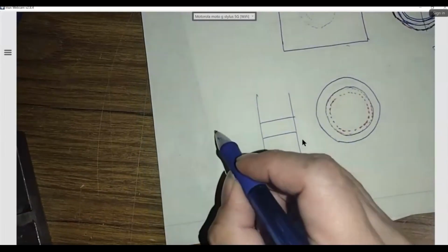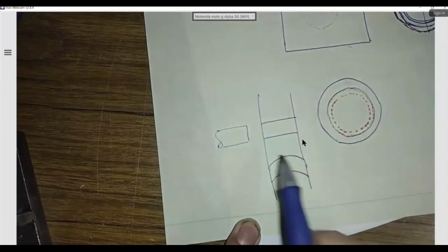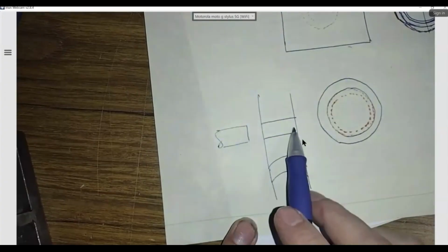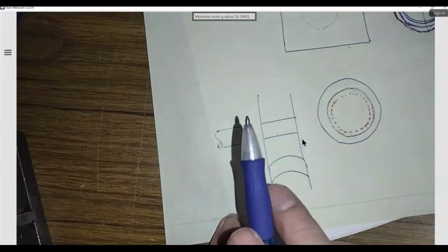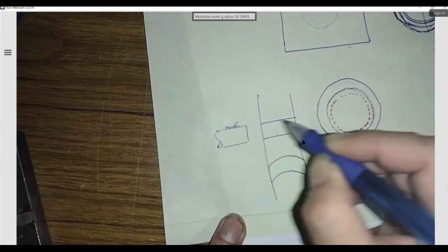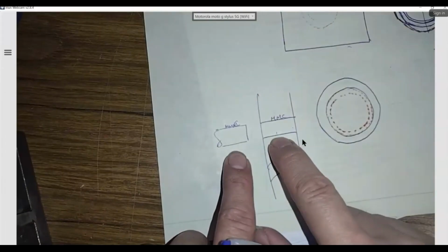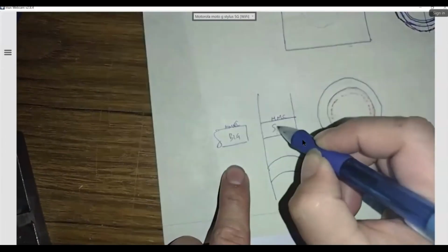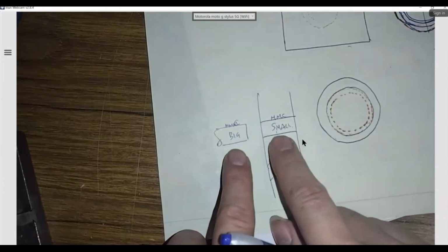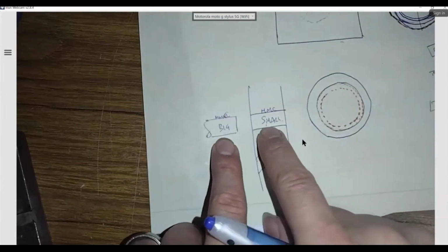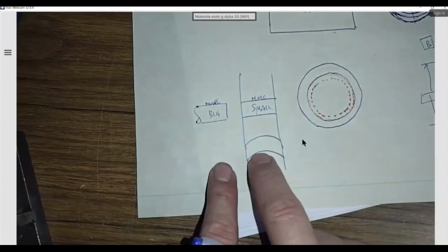What happened to a pin? So if I were to have the pin, and my hole were to be perfectly straight, even at the worst case condition of the hole, which is called the MMC, will have to fit in the MMC of the pin. So again, both of them will be in the worst case condition. The big one and the small one. And it will fit. But that happens when it's perfect. And nothing's perfect, by the way. Right? So what happened to the hole?